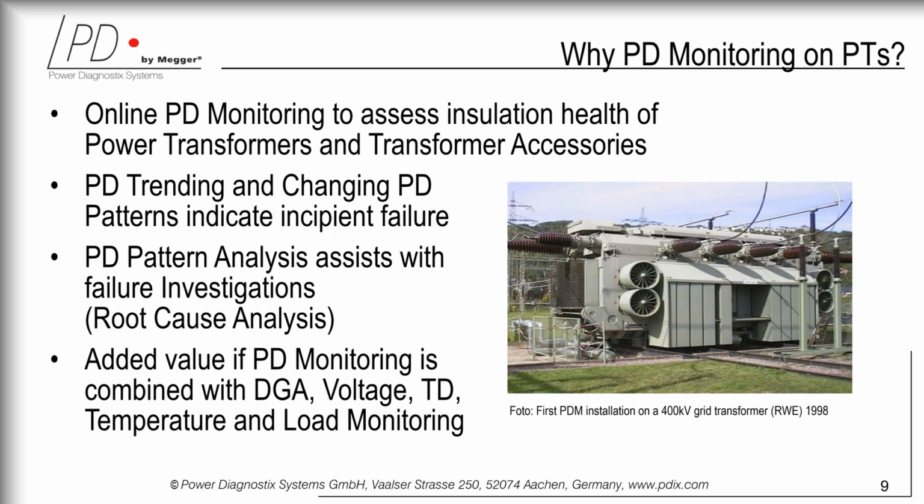Of course, a transformer, based on its criticality, as I discussed, can be loaded with all these sensors. Of course, these sensors have a cost. So then there is an optimal ratio between the cost of the transformer and such sensors, and I would say that optimality is given by the criticality and the price of that particular asset.